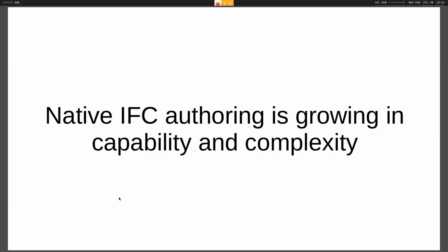There's also this emerging concept of native IFC, which is the extreme of it, where users create IFCs directly. There's no translation from other schemas or data structures, which is kind of the natural progression as IFC gets more feature-rich and people get access to it. It's no longer necessary to switch to and from IFC. So because there's no import or export, the MVD concept starts to apply less and less. This is in contrast to the more traditional translated IFCs. So this kind of new partial or native IFC manipulation might suggest a new form or category of certification to cater for it.